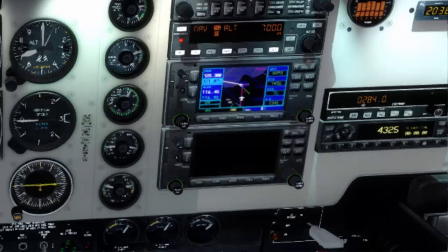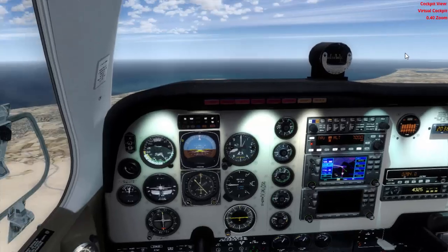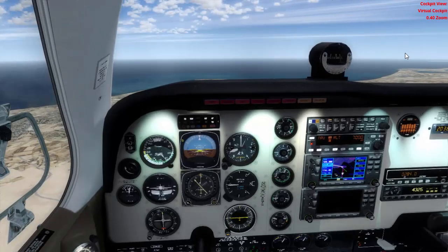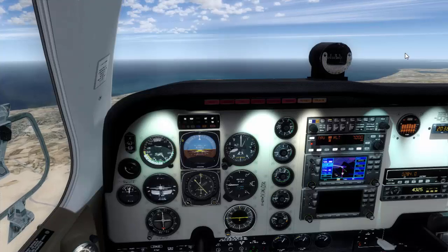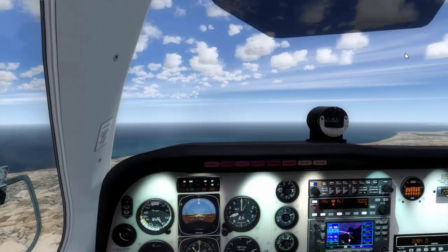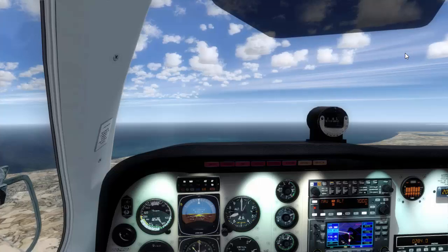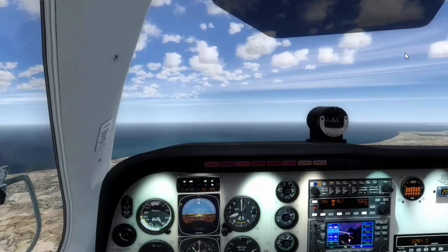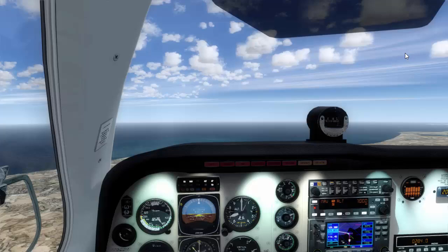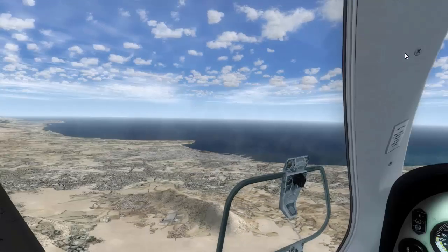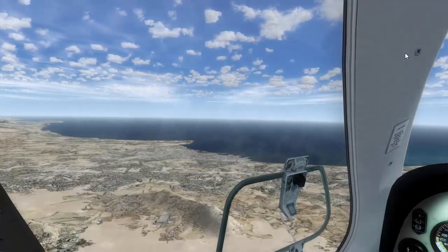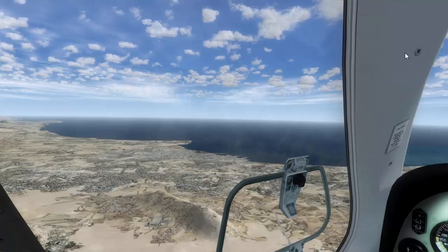Okay, so take a look to the flight plan in our GPS, and we will be reaching very soon the VOR, the Alicante VOR. And remember what I told you before, that we won't reach that VOR by following any of its radials. We will be reaching that VOR just by flying to its geographical coordinate. Okay, I want to emphasize that again.